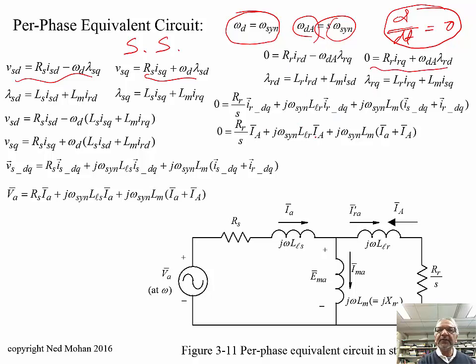And so where is the rotor circuit voltage? This is for the q-axis, and this is for the d-axis here. And the flux linkages here we can write. I don't need to go through it in detail. And then we can express these flux linkages in terms of the currents and mutual inductances. So we get these 2 equations here, and then we can make them into a space vector Vs dq by multiplying this second equation here by a factor of j, right?